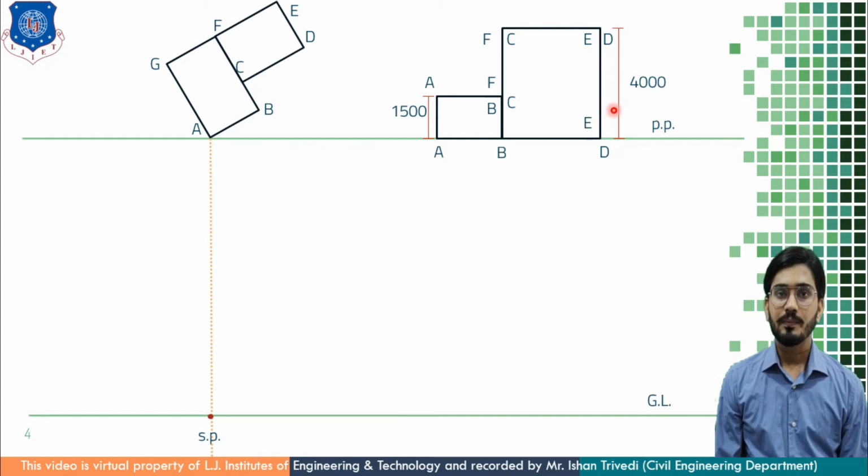Even in the first example, I can do the same and my drawing is not going to change. But for your first exercise, I kept these three components, station point, vanishing point and ground line, separate. But here, the ground line passes through the station point itself.